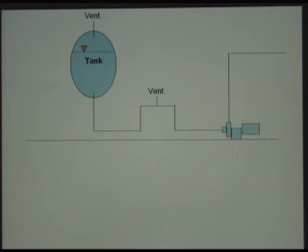One of the corollaries to that is if we have a high point into the pump suction that's below the fluid level, it will be self-priming. But in this location here, you're going to have trapped gas, which needs to get vented off. So we need to have what's called a high point vent. The operators will open up until fluid passes out of it to get rid of any trapped air that may be in that location. And they'll do that before they actually start the pump up.